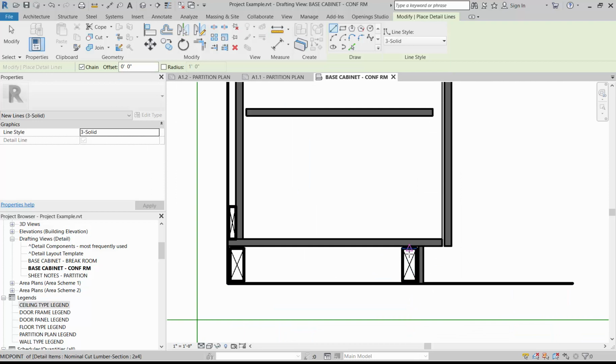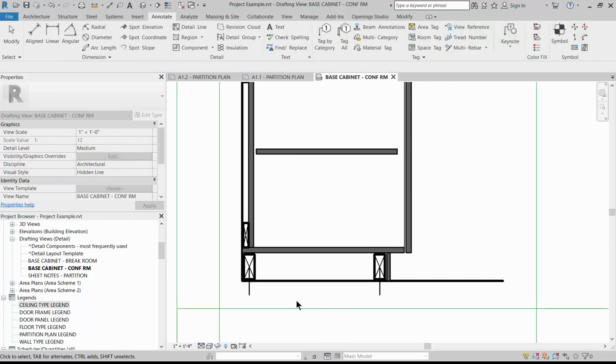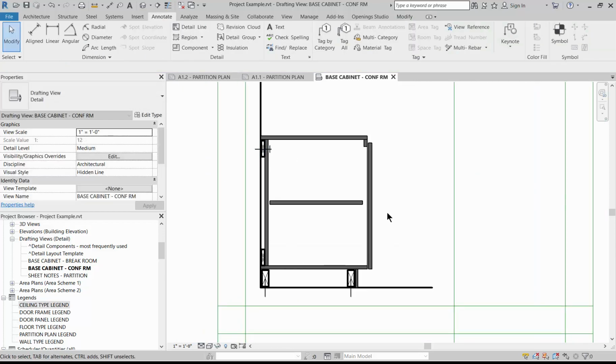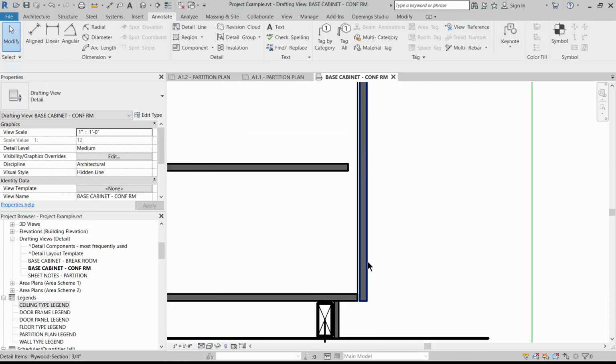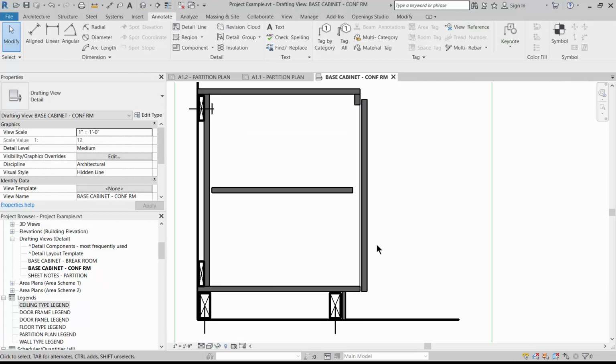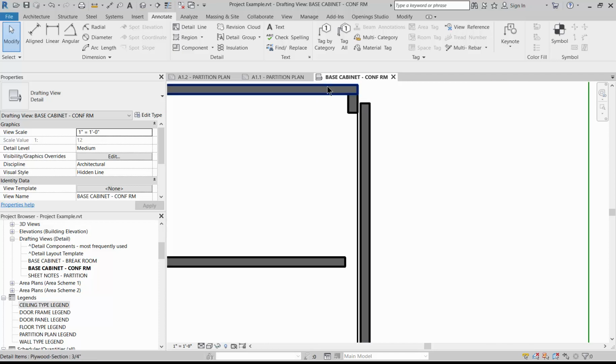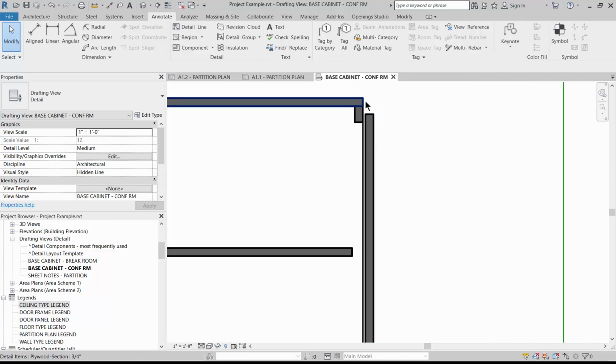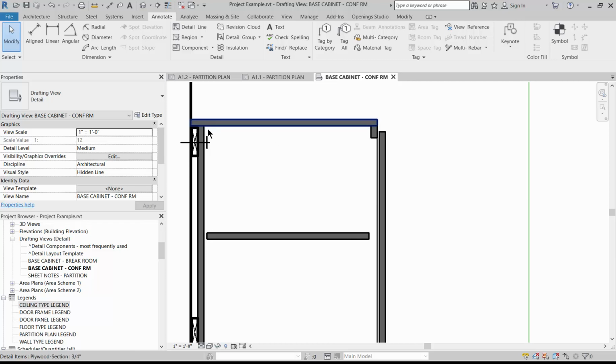And I would also note that these pieces are attached to the ground. So we usually, the base cabinets, they are anchored to the ground and then to the wall so they don't tip over. I'm assuming a flush overlay door, so the door overlays the cabinet, and here at the top I left a little bit of extra space to build out the countertop around it. I might actually have another layer here to wrap laminate countertop, or if I have a solid surface counter, which I'm going to show it this way.